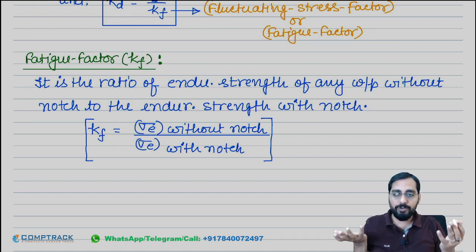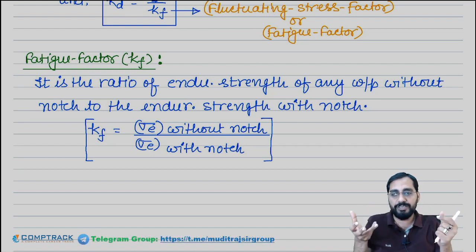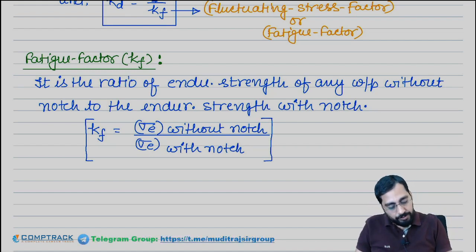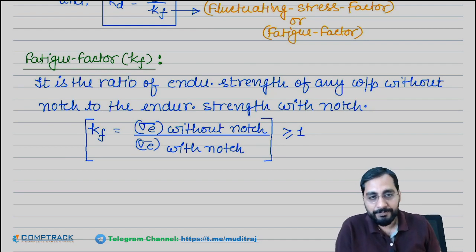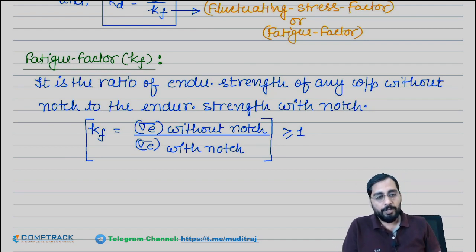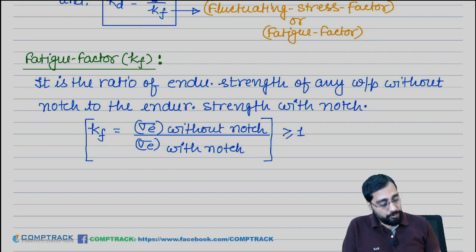Yes, without notch the strength will be more. With a notch there will be stress concentration. Okay, so this Kf will generally be more than or equal to 1, more than 1 generally.